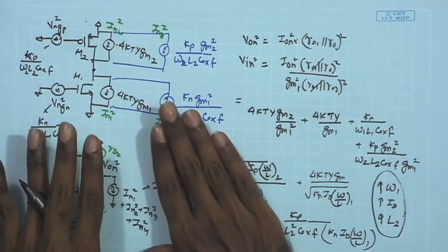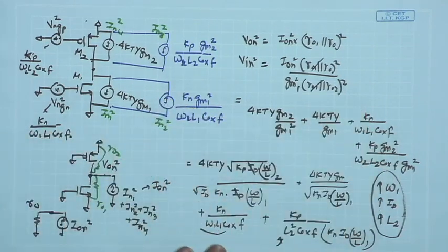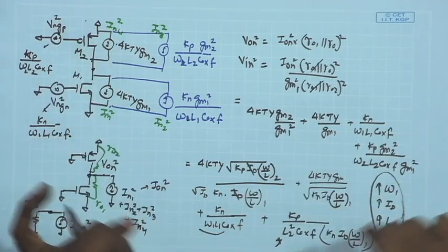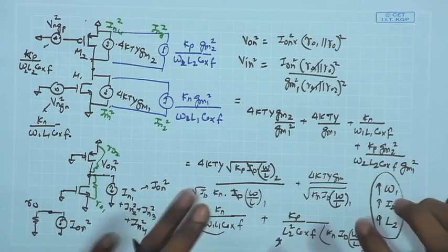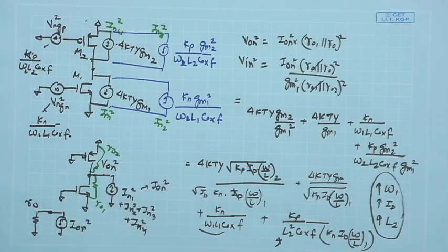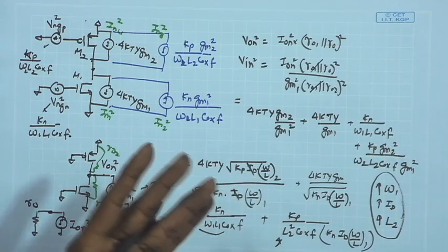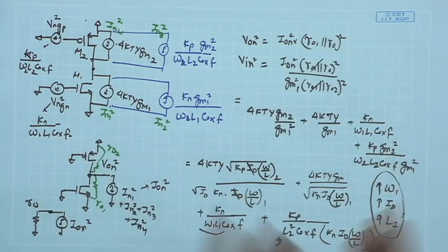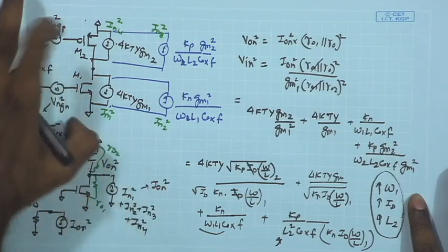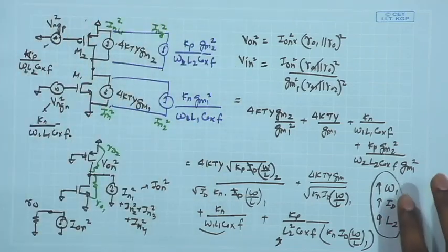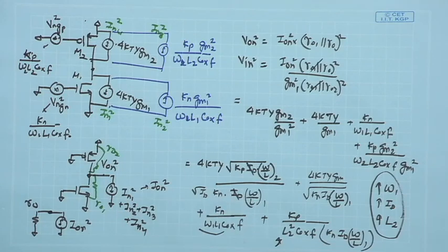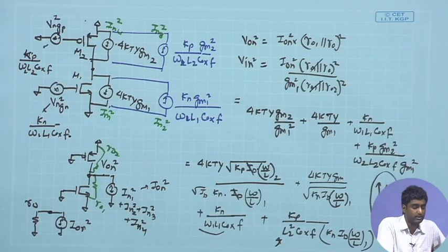And also we need to look at the differential amplifier configuration, and at how the noise contribution of the transistors affects the response of the fully differential amplifier with which we are building our op-amp. At the starting point, we can say that ultimately the differential amplifier, for the differential response, has an AC ground over here, so it boils down to the same common source amplifier. So it should not create a lot of difference, but only a minor point needs to be addressed, like the tail current source. So that is another small issue that we can address.